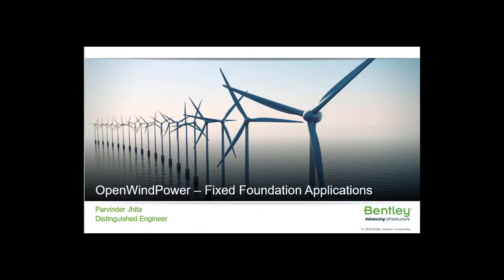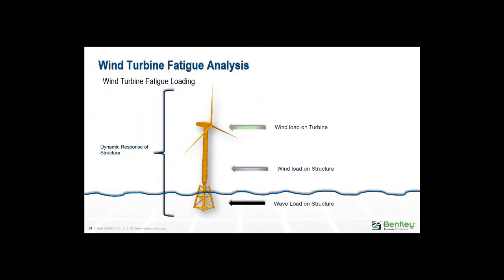Next, I'd like to discuss the fixed foundation applications we have. It's a typical wind turbine structure here. We have three sources of loading. We have the wind load on the turbine, wind load on the structure, and the wave load on the structure. The dynamic response of the structure is coupled to all these three sources of loading. So we'll talk about coupled and uncoupled analysis later on.